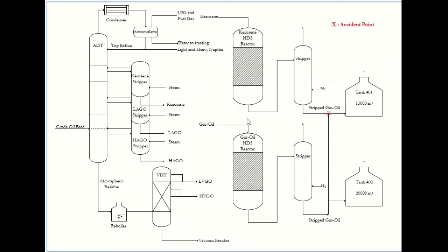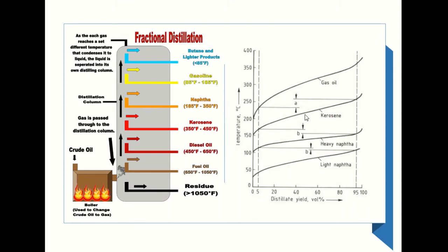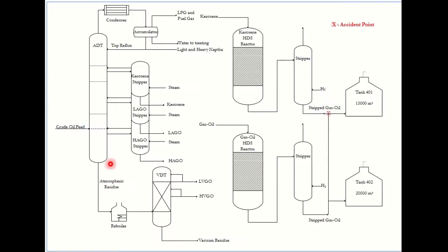So in this case, the hydrocarbon fractions with boiling curve above 360 degrees Celsius should not be recovered by the atmospheric distillation because the cracking of the heavier products starts above this temperature. Therefore, the atmospheric residue must be subjected to a vacuum distillation.